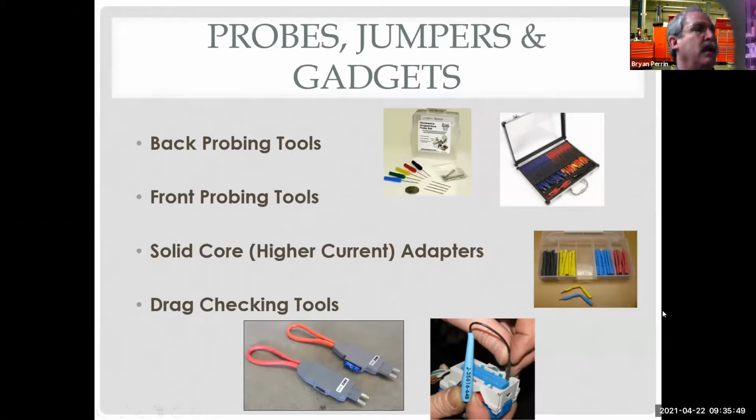So here we have a connector, and a connector in this case has a lot of female pins. And what happens is the female pins open up, so I'm not getting a good connection. And this problem has gotten worse because the pins have gotten smaller. We're now down to 32 thousandths diameter pins. So the simple weight of a connector that someone didn't secure can be enough to damage the female portion of the pin connection. And once they get loose, now we don't make a good electrical connection.